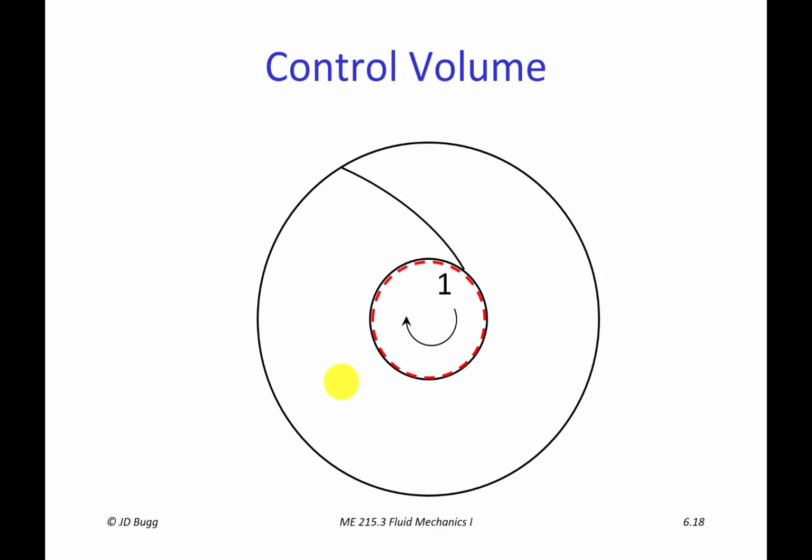So the inlet of the control volume is going to be this cylindrical surface. I've shown a red dotted circle there, but the surface that the fluid is entering our control volume through is actually a cylinder. So imagine that circle protruding in and out of the screen a certain distance, and the thickness of the impeller in that direction, perpendicular to the screen, is an important parameter that we're going to bring into the analysis later. So there's a cylindrical surface there, and the fluid is crossing that surface and entering into the control volume. So flowing radially into the control volume through that surface.